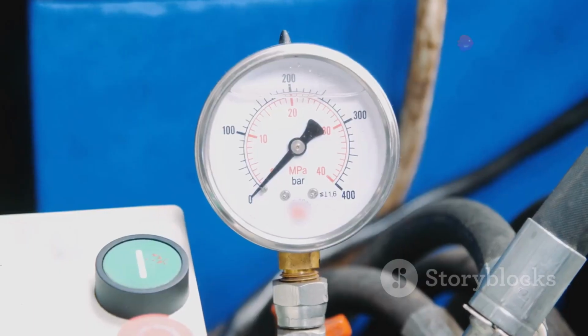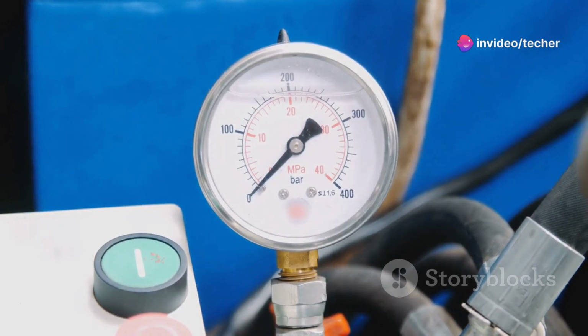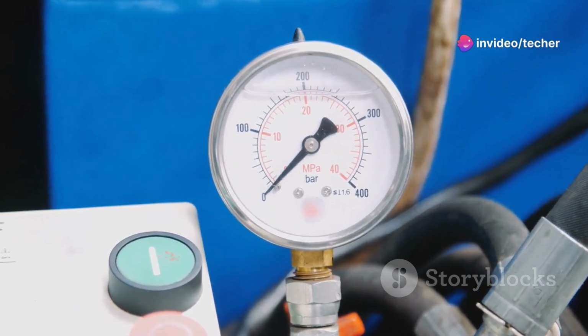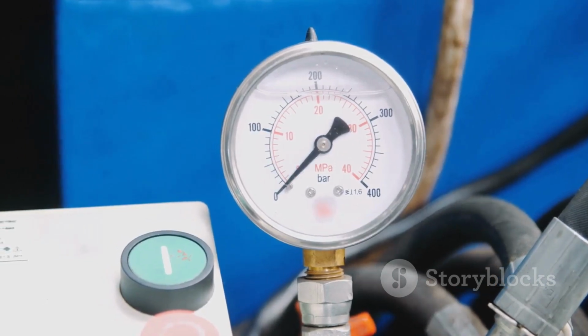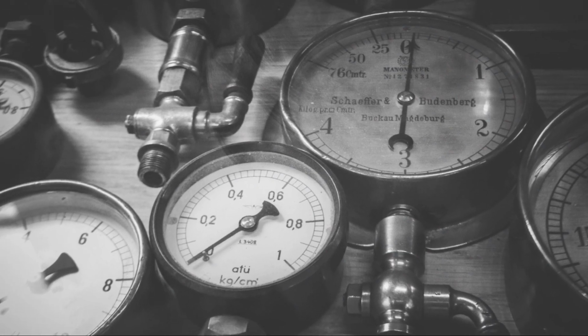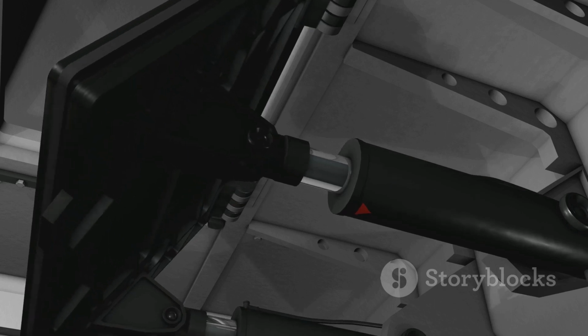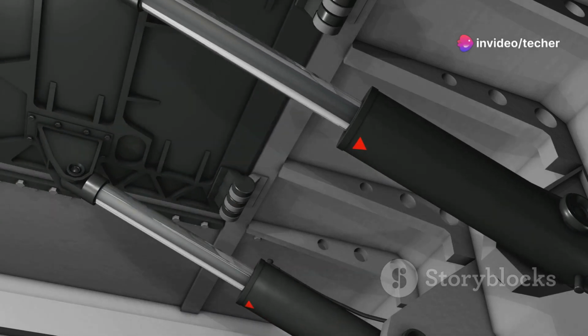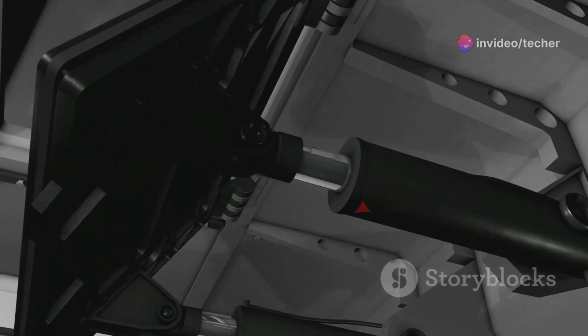Digital pressure sensors, on the other hand, provide a discrete output signal, typically in the form of a high or low voltage level, indicating whether the measured pressure is above or below a predetermined threshold. These sensors are often used in applications requiring simple on-off control based on pressure changes, such as detecting the presence of an object or triggering an alarm system.